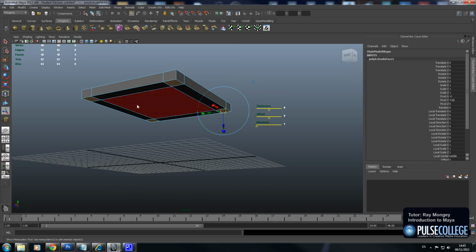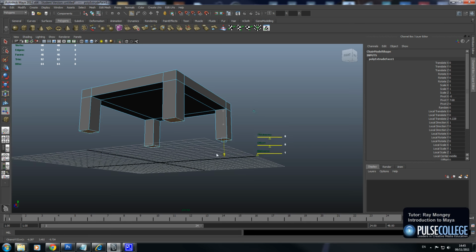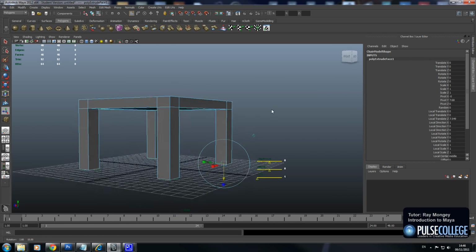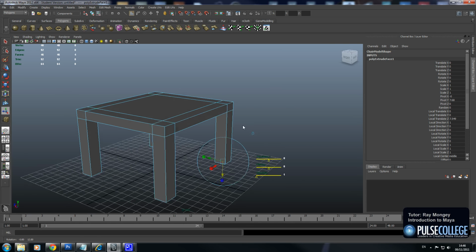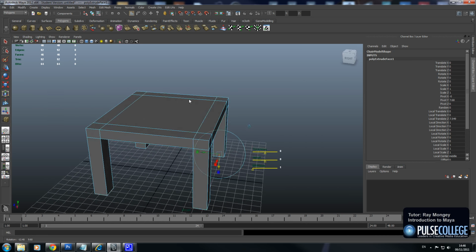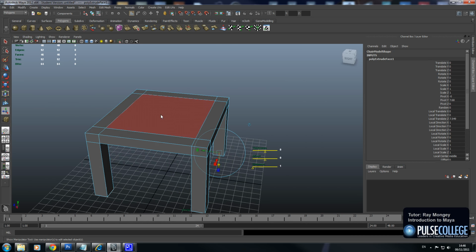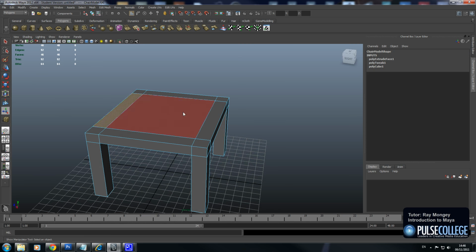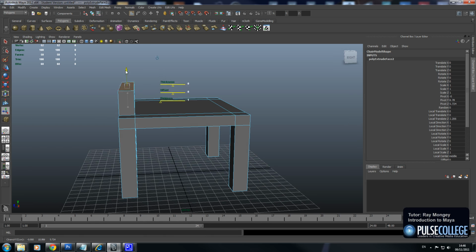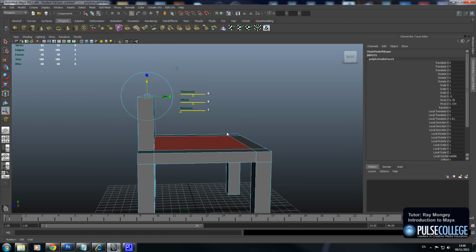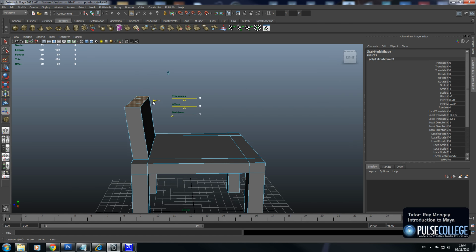So now we can click on this arrow and drag that down to wherever it meets the grid. It doesn't have to be precise at the minute, but we can also go in there and start scaling that. Because the extrude operation was the last one that we selected, the next face that we select, we can then just hit the G key and that will go to extrude, and now we can pull out this face. Alt middle mouse button to drag it down to view it at a different angle. Maybe we want to move this face just back a bit,